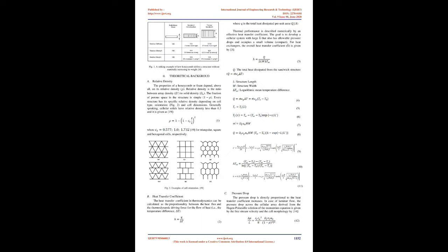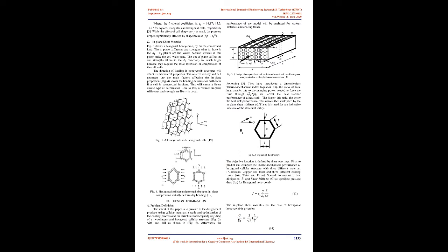The simplest kind of sandwich comprises two thin, strong sheets of dense material separated by a thick layer of low-density material which might be substantially less stiff and strong. This ensures that the bending stiffness of the sandwich is much greater than that of a single solid plate of the same total weight made of the same material. The core must be stiff enough in the direction perpendicular to the faces. This will guarantee that they remain the correct distance apart, and stiff enough in shear to ensure that when the panel is subjected to a bending moment, the faces do not slide over each other.